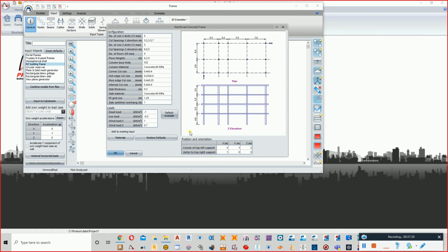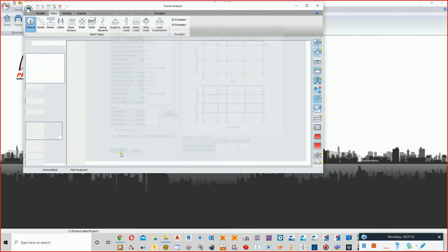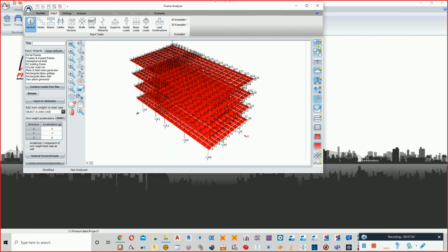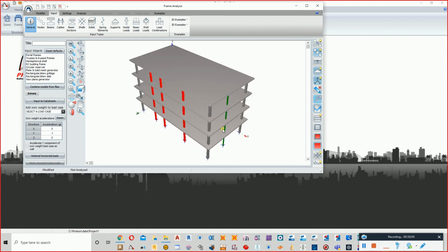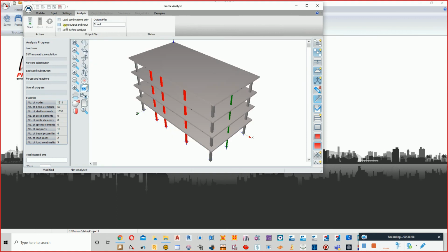Okay. Now, loads, you can put the loads on the slabs directly. So that load, live load, for example, minus 5, and then live load, for example, minus 3, and then wind load now I don't want. Okay. And then click on OK. You can see this has been shown for you, and you can see the 3D here where we are having the slabs and upper columns in a flat slab system,